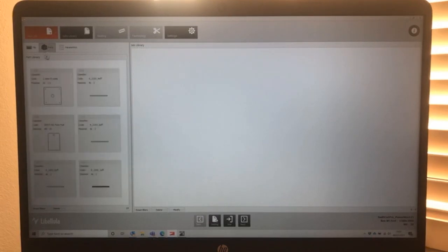The parts list, which is another drop-down selection tab, contains all the parts that you've previously loaded into the system. Once you've created them as a part in here, it will save automatically into the parts list. The parts list is very good in that it is filterable by the materials that you are working on. So if you load a full sheet of material onto the bed, and you nest the parts that you need, and there's a small gap at the top, you can filter the components within the parts list to effectively fill in the gap.